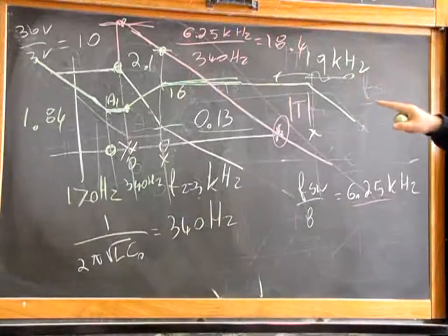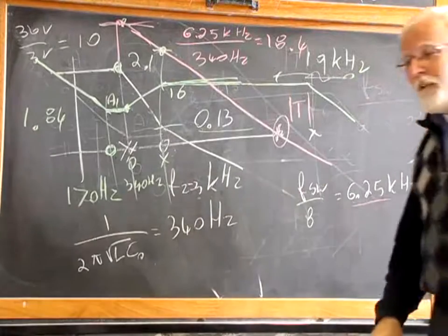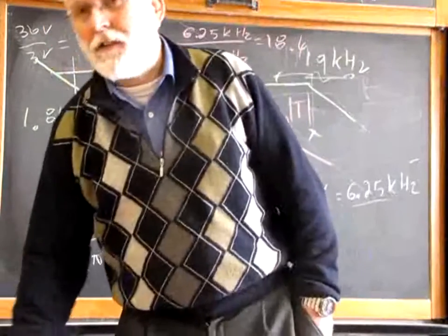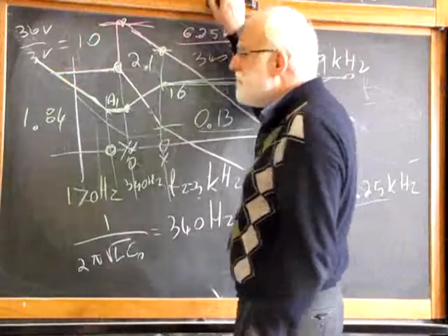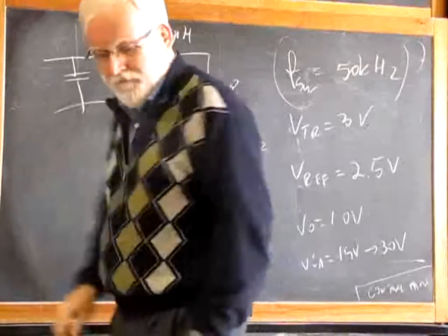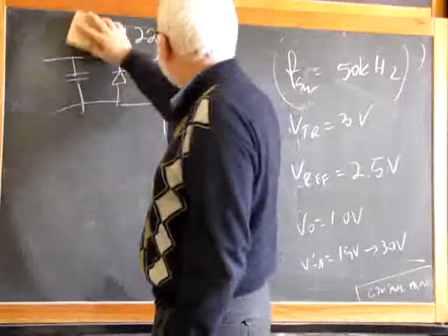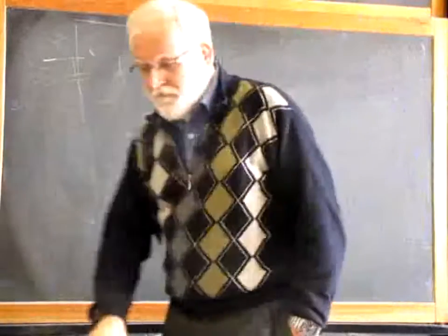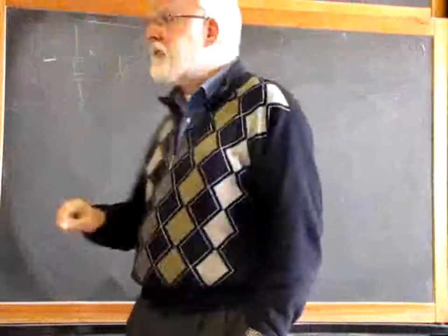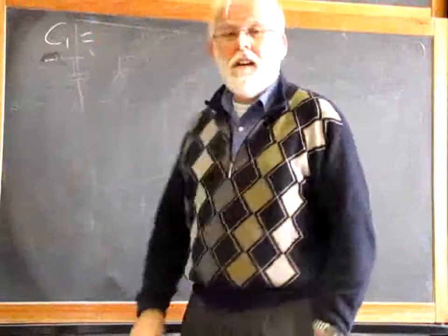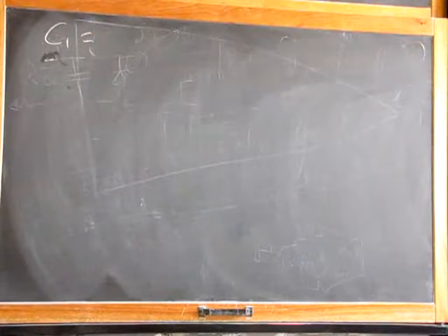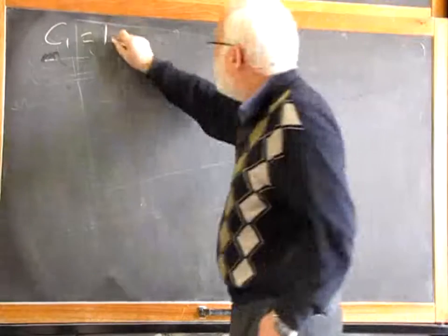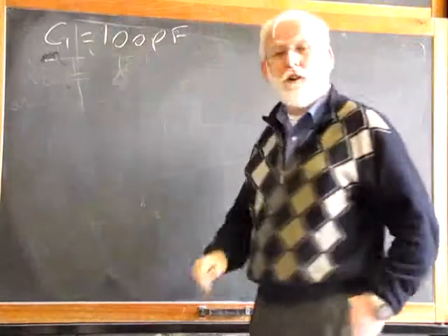Okay, all the numbers are there, and we can just use our equations we derived earlier to find out the component values. We start to assume a value for C1. And as usual, C1 go from 100 picofarads or less, a few tens of picofarads, to 1 nanofarad or less. So C1, 100 picofarads is my choice for today.